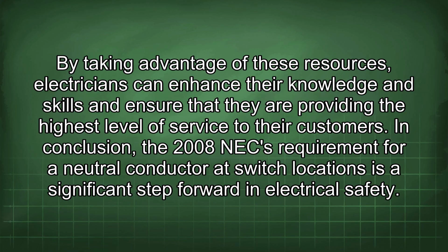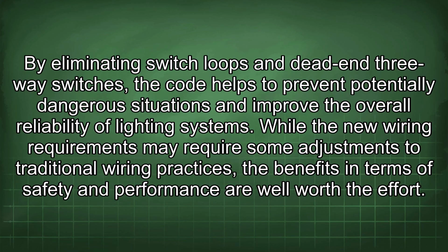In conclusion, the 2008 NEC requirement for a neutral conductor at switch locations is a significant step forward in electrical safety. By eliminating switch loops and dead-end three-way switches, the code helps to prevent potentially dangerous situations and improve the overall reliability of lighting systems. While the new wiring requirements may require some adjustments to traditional wiring practices, the benefits in terms of safety and performance are well worth the effort.